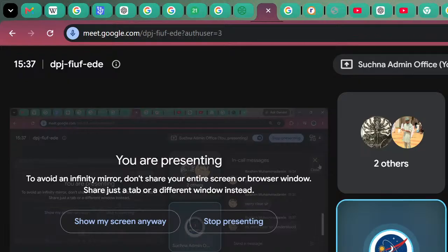So today we discussed the ULN2003A Darlington transistor array, which is used to protect the main microcontroller from being damaged by the reverse flyback current. It acts like a sink for current up to 500 milliamps. It has flyback diodes which suppress the reverse current and clamp it to the ground, discharging the current into the ground, so that you can safely operate relay modules with any microcontroller.